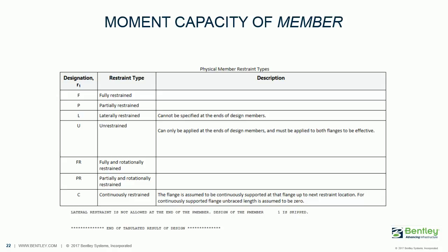And the continuously restrained is something like you have the critical flange restraint provided continuously by the concrete slab or the checkered plate, or any sort of diaphragm or a timber floor, etc. So all these types of restraint conditions can be assigned in Staad.Pro, and you can simulate those restraint conditions.